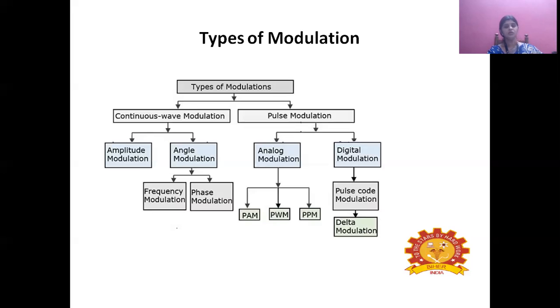So the analog to digital conversion process consists of three steps. One is called sampling, another is quantization, and the other is called encoding. In the sampling, the samples of the continuous time signal are obtained at fixed intervals of time. So after sampling, you will get samples which are fixed in time interval, but their amplitude levels will be varying. So the next step is quantization.